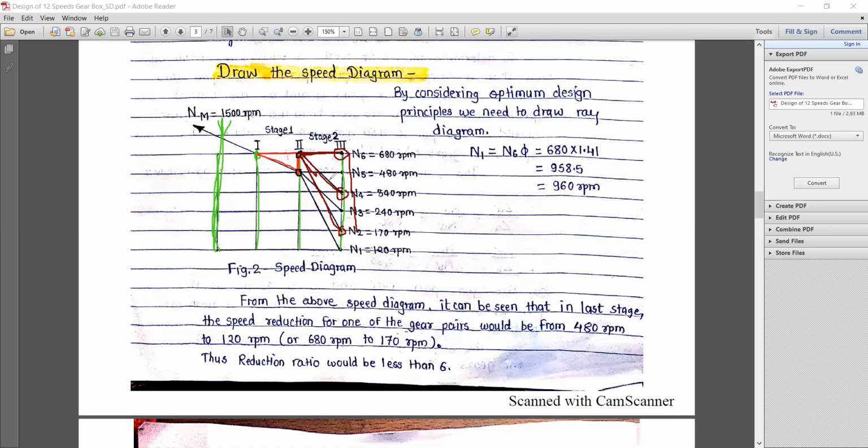Now we need to find another 3 speeds. So I am referring to this point now. I have drawn in the same way, and I drew the first point over here. Then the spindle speed spacing is 2, so this is a spacing of 2. I got this point and connected from this to this. Again the spacing is 2, so connecting with a spacing of 2, we received this point. Connect from this to this. So you can achieve these 6 different output speeds.